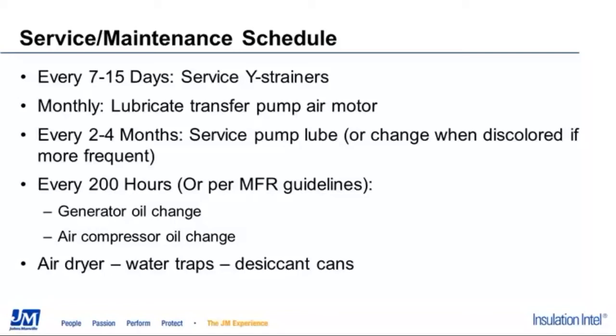Looking at the monthly area, we look at the transfer pumps. On the transfer pump, we have the air motor that sticks out. We're really talking about T1s, T2s, IPM01 series, 02 series. There's a handful of others out there. But on that air motor with the air disconnected, we want to remove the cylinder and the top cap, wipe out the old grease, just freshen it up, put in some new grease, close it back up, and then do that once every month.